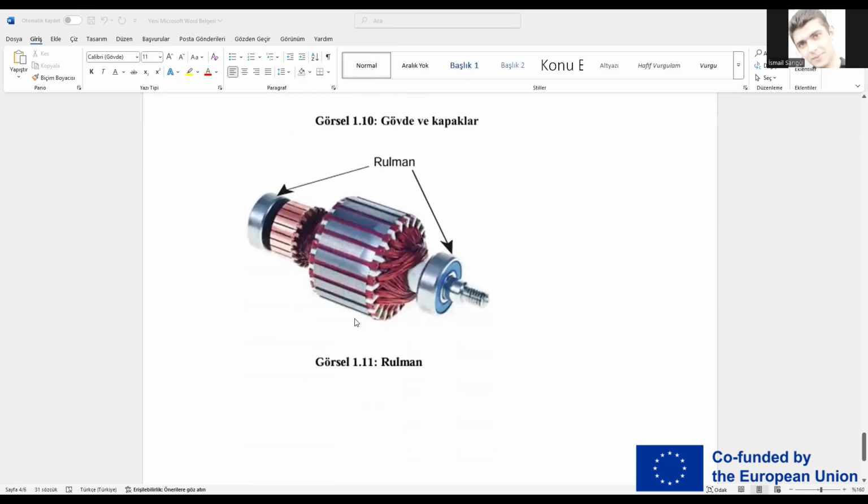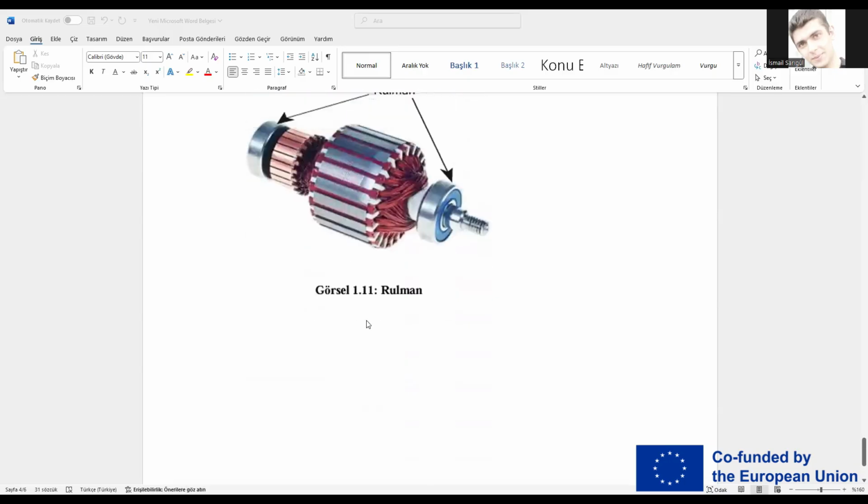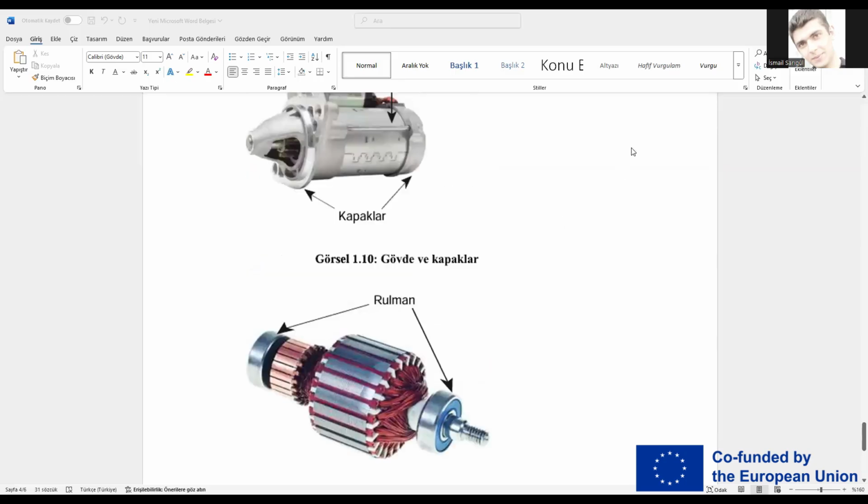The last figure is bearings and seats. Bearings enable low-friction rotation. Deep groove ball bearings are typical. Proper lubrication, load rating, and alignment govern service life. Lack of lubrication causes wear and noise. Incorrect installation or removal promises damage. Tolerance in the bearing seats and shields controls rotor runout and air gap uniformity. Thanks for watching this video.